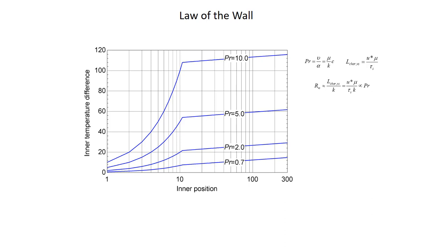So if I want to think about the thermal resistance of the viscous sublayer, which is the biggest thermal resistance in a turbulent flow, it's going to be how far do I have to conduct the energy, which is the size of the viscous sublayer, which is at least proportional to this characteristic viscous sublayer length scale that we found before, right?